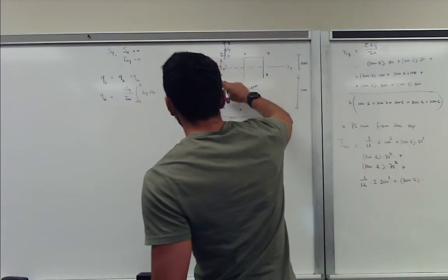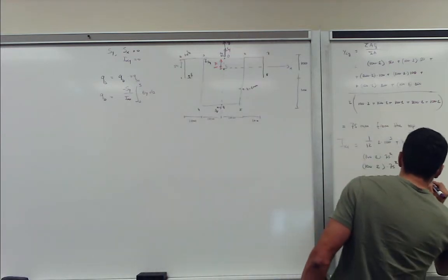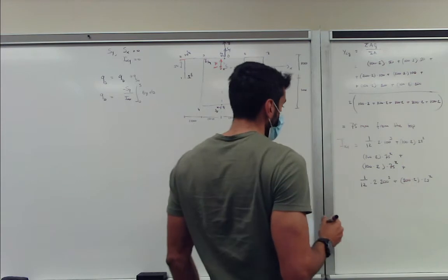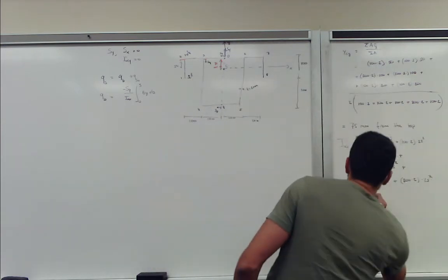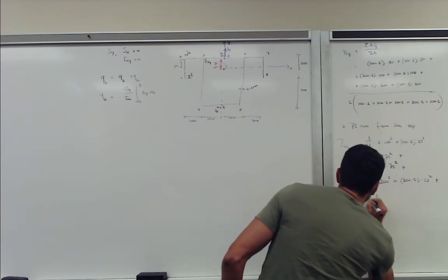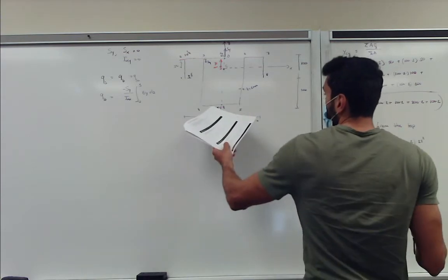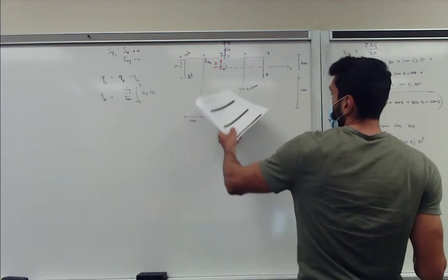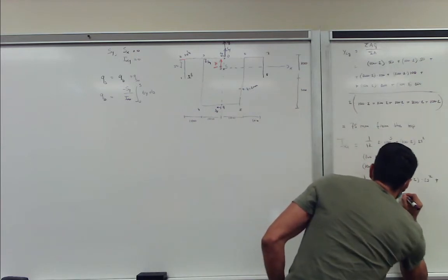This lies at 75, so it's shifting up 25. So 25 squared is the AD squared term. And then we get these two axes, 4-5, which again is just the standard term. So area times 2 multiplied by the distance, which is 200 minus 75, so 125 squared.